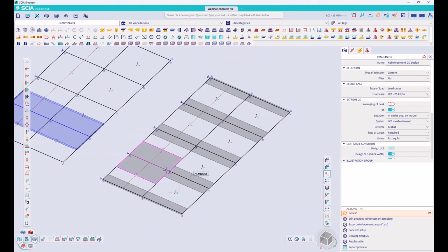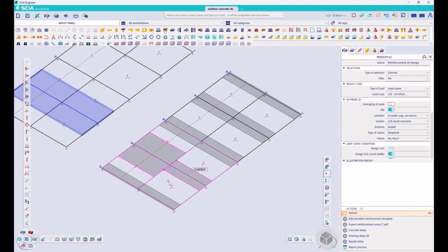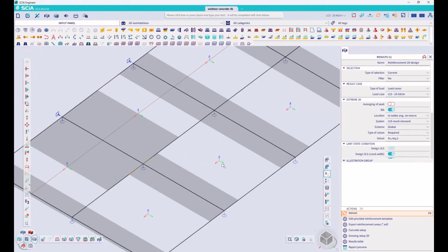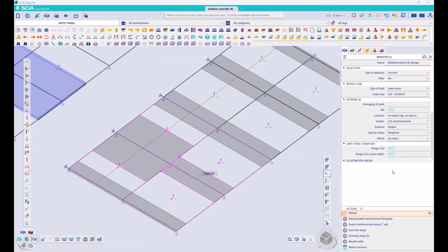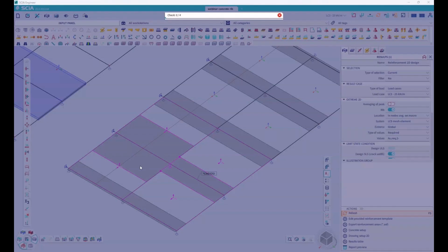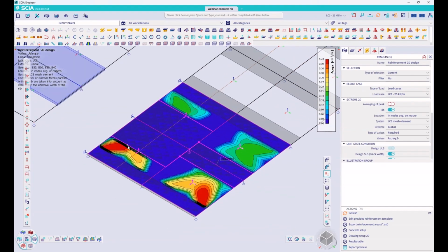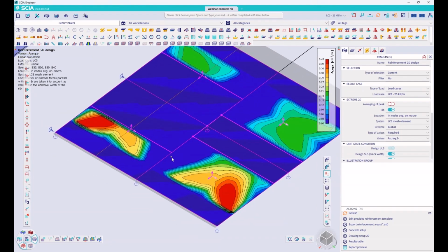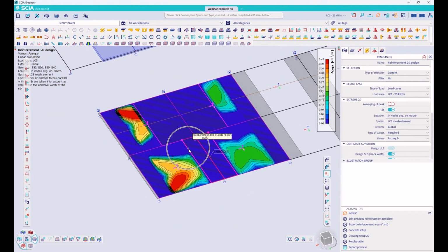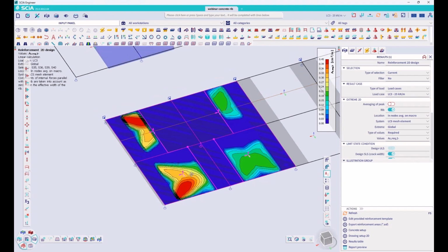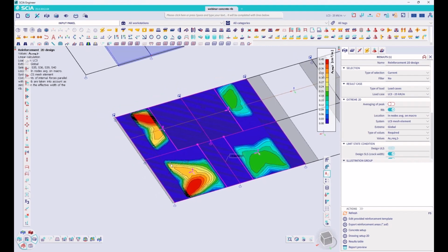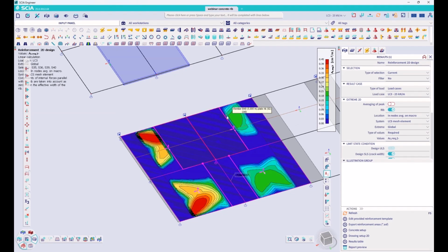And if you take a look at, for example, the reinforcement in these 4 plates, let's say the second direction at the bottom, so in the y direction, the direction of the green arrow, we should be able to see that in these zones of the rib there is no reinforcement necessary. You can see the blue zones, there is no bottom reinforcement necessary. And you can see that with the model where we took fewer forces into account, I need more reinforcement in the plate, or over a larger zone, compared to the model where I took these forces into account in the rib itself.